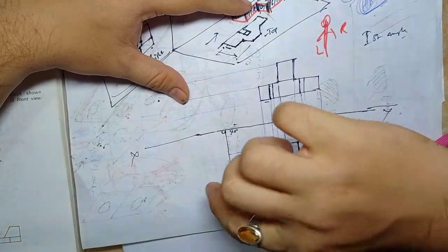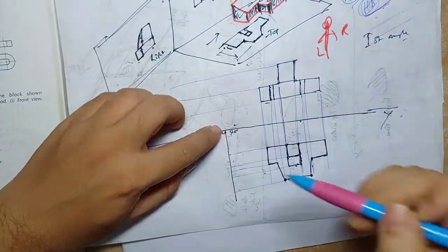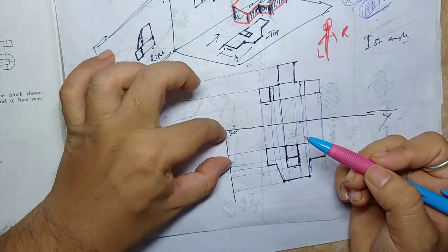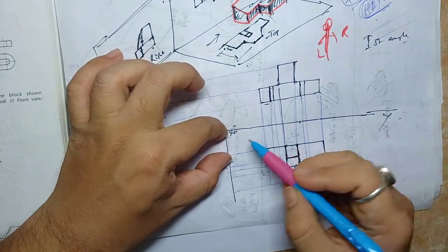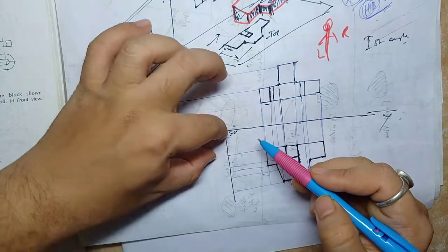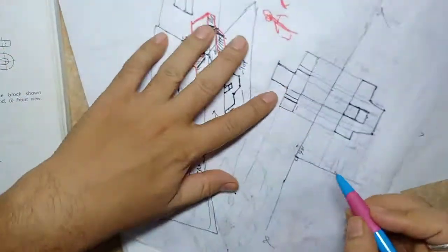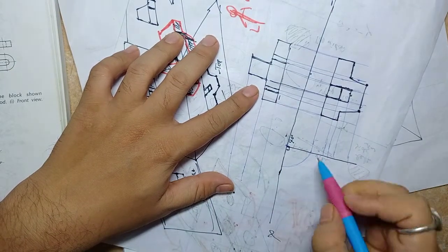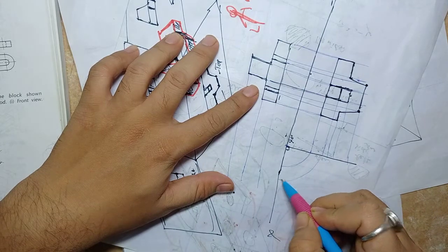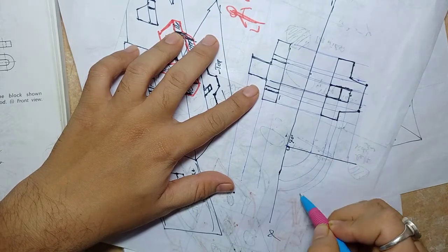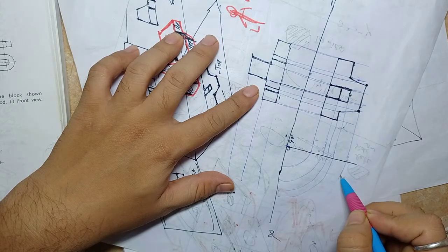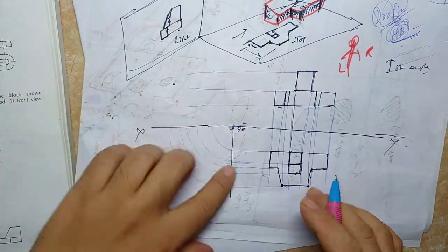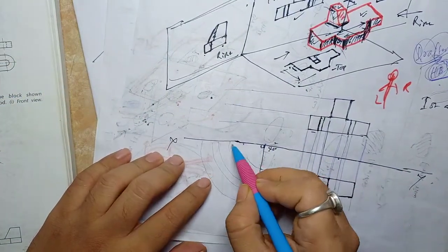Now take a compass, take this point as the center, and take your radius here exactly equal to this much, and then you rotate 90 degrees. Draw your quarter circles, taking the radius here equal to this one, here also similar to this one, similar to this one, exactly equal to this much. Understood? So you have completely rotated your lines to strike your xy line here.